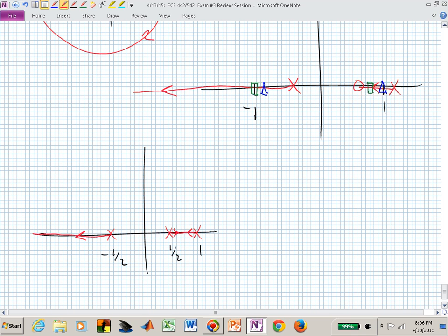So if I have 3 poles at the same location, where must I be standing, at what angle away from that centroid, in order for those 3 angles, they're going to all 3 give me the same angle, but those 3 angles have to sum up to minus 180 to be on the root locus? So it's going to be at 60 degrees, isn't it? I have a 60, a 60, and a 60. I'm going to subtract all 3 of those, and I'm going to be at minus 180.